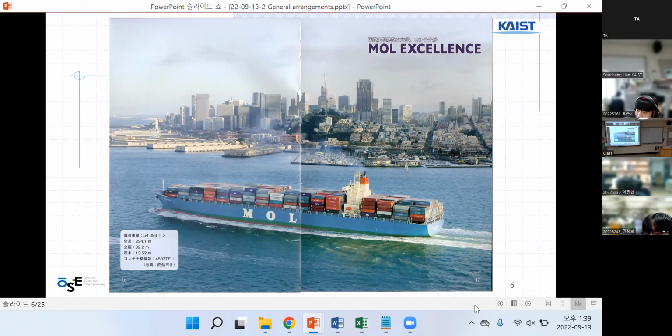Now, Panama has another canal, opened 2 years ago, and that big new canal can allow 50-meter breadth ships. And this one is very special, so I can identify it by using this number only. We call this Panamax, the maximum Panama pass-through ships. And draft is 13, container 4,800 TEU.